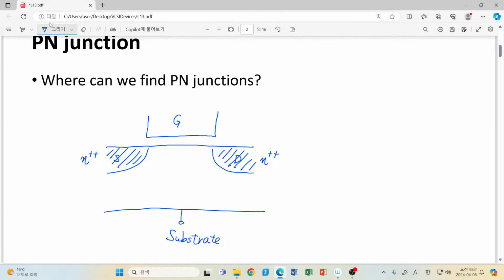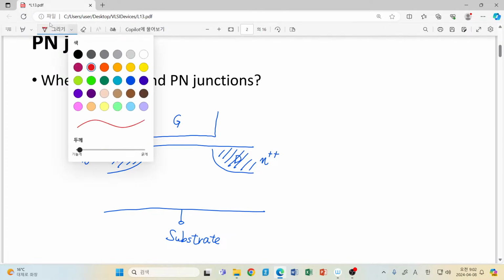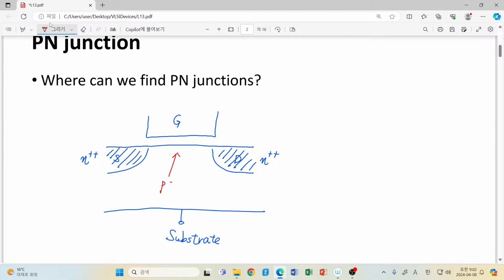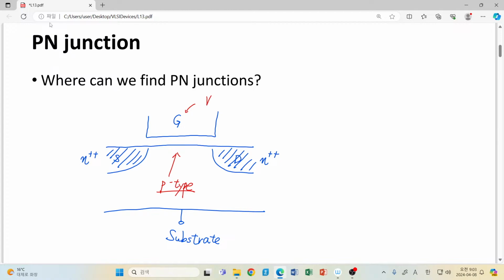However, since we have introduced a certain p-type region, without the assistance of the gate bias voltage, the conduction path between the source part and the drain part is disconnected. Only when we apply a sufficiently high gate voltage can we connect both regions by a certain inversion charge layer.